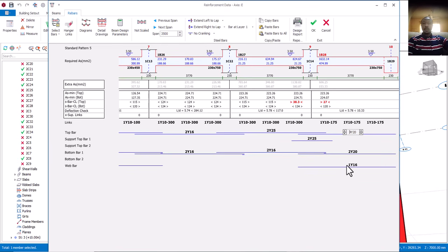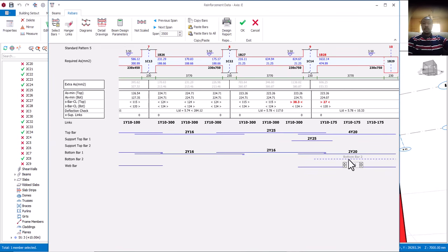Is that okay? All right, so in this case, now that we're having up to 750 beam depth, automatically I'm going to use a minimum of 2 web bars. If it's 650, I'll just use one web bar, but 750 is going to be 2 web bars, etc. All right, now this place that is showing red, no problem. Why? Because my quartz aggregate can still pass, because the quartz aggregate they are going to be using is 20 mm and I have 25, which means that yes, my quartz aggregate can pass through this reinforcement.